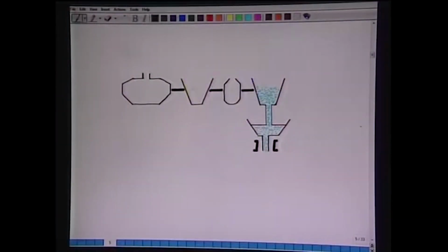Now, after this, let us see the iron and steel industry where the refractories are used. Here I have just shown a schematic sketch of various vessels where refractory materials are used. The first one is a torpedo vessel. Now, this torpedo vessel typically handles hot metal from blast furnace and transfers it to the LD steel making.